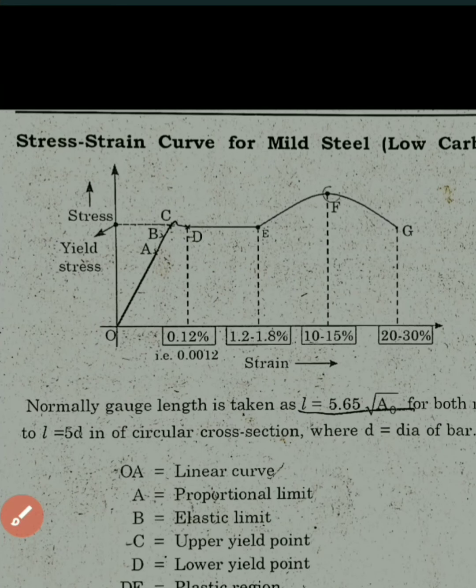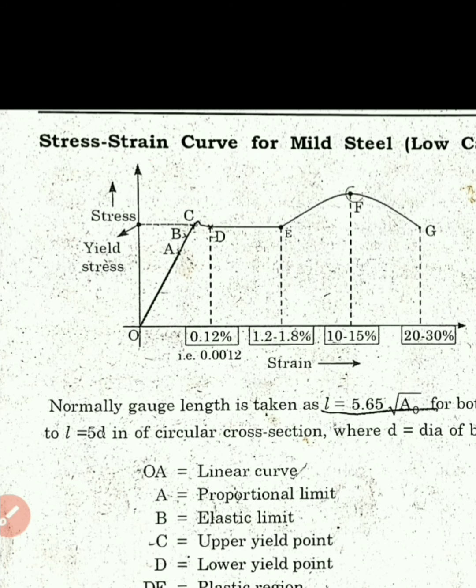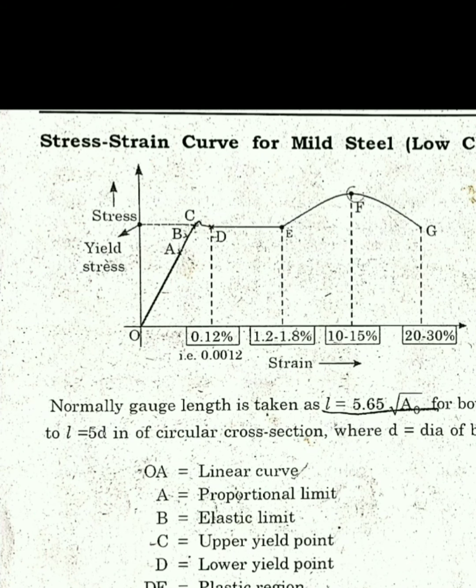Necking starts occurring in the material. So because of necking, what happened? The diameter of the portion of the specimen begins to decrease because of local instability, and after necking begins, lower loads are sufficient to keep the specimen elongating further until it finally ruptures.